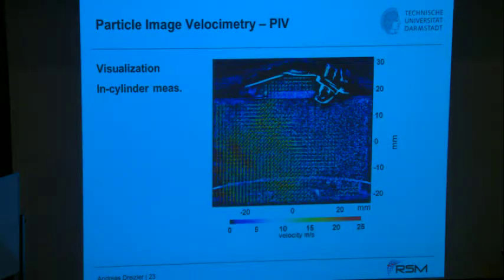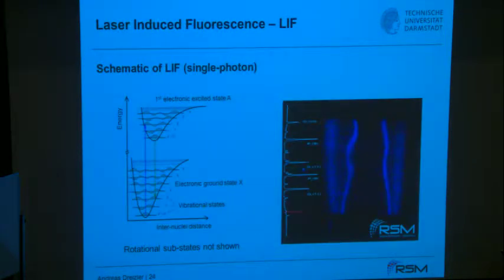So you do this correlation to deduce the velocities. That is combined with the OH PLIF. We have seen that as well earlier this week, where you excite at 283 and then fix your laser at a certain transition and measure the relative intensities in OH, where you visualize the flame front. Quenching is not considered typically, but the intensity profile typically is considered.